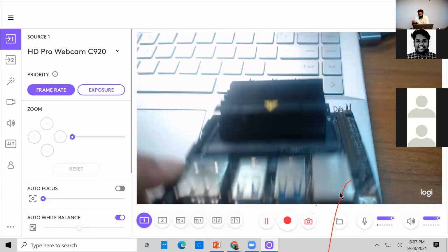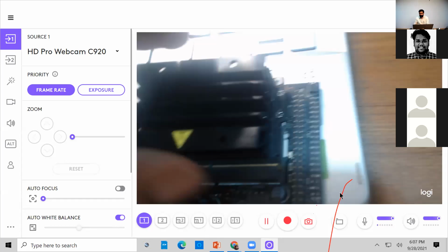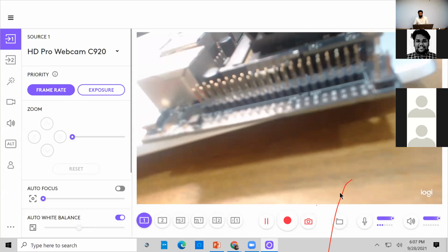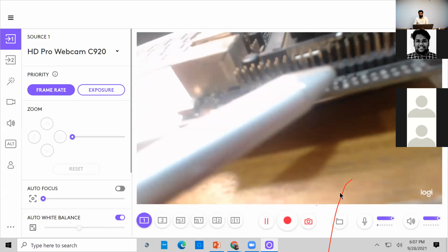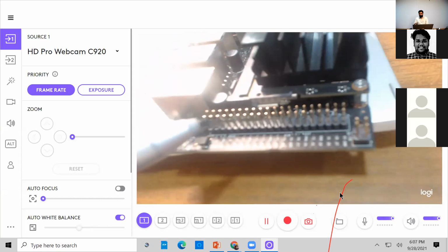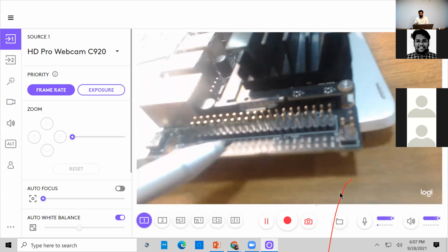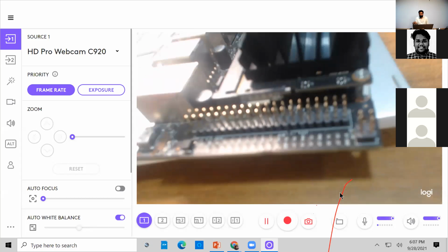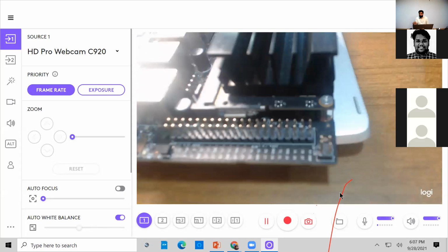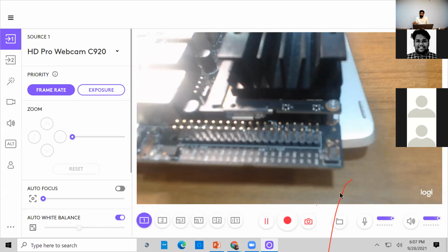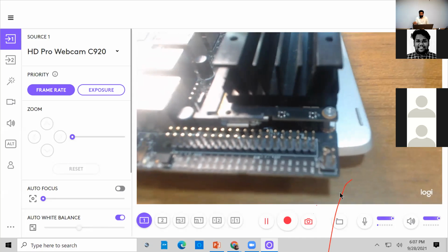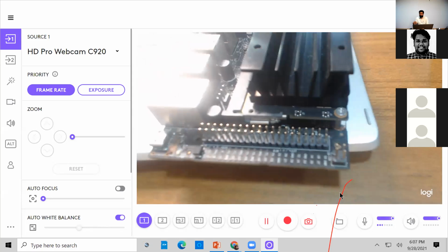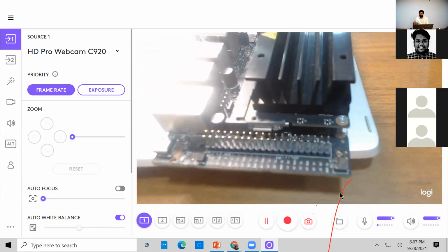In addition to this, similar to your Raspberry Pi board, it also has a GPIO header, a 40-pin GPIO available on your Jetson Nano. Mostly these GPIO pins are used to interface sensor devices or devices from the external world, especially in the form of digital communication data. But it also supports analog sensor interfacing with an additional analog to digital converter.